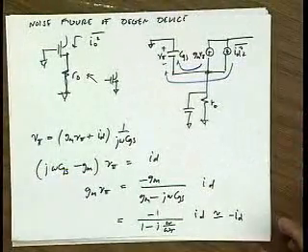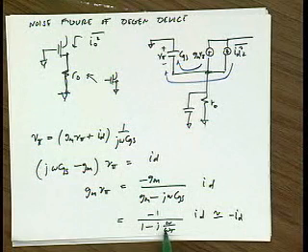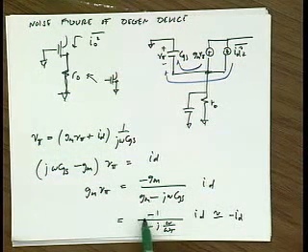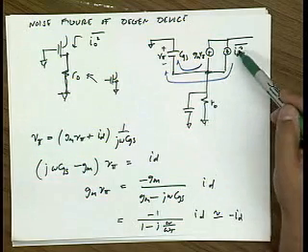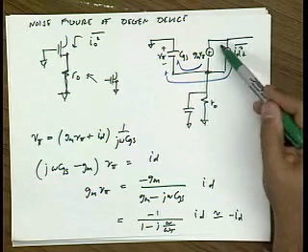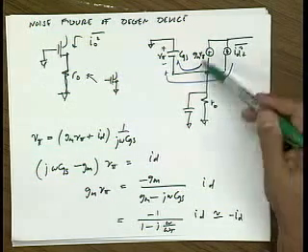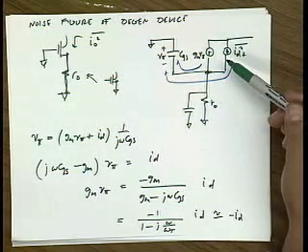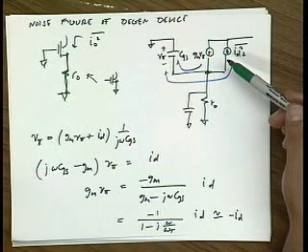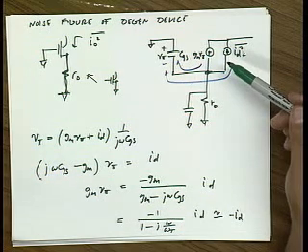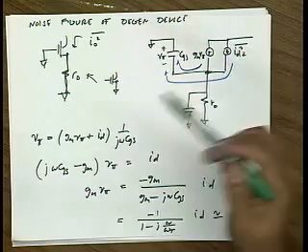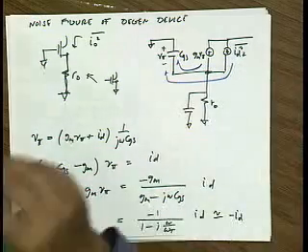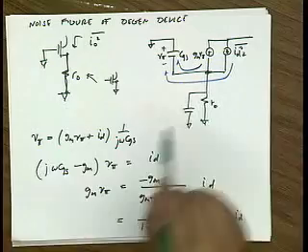So what I've just shown you is that if frequency omega is much less than omega t, this term goes away, this is minus 1, and therefore almost all the noise of this device flows through this gm generator. So this device contributes nearly no noise at all. If the frequency is really lower than omega t, then no current goes through CGS, it all goes through. That's a good point. There's another way to look at it which explains that condition, but let's stick with this for the moment.